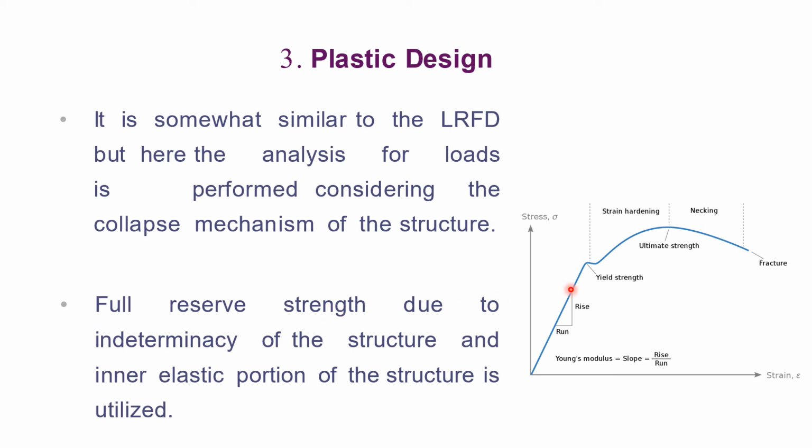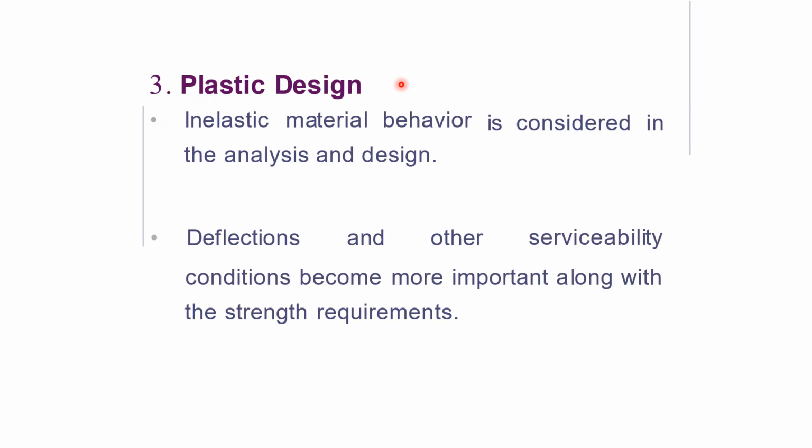Full reserve strength. You can say this is the reserve strength. We use LRFD only within the elastic range, not going into the plastic range. But in plastic design we also go into this plastic range, the permanent deformation. Full reserve strength due to indeterminacy of the structure, the inelastic portion of the structure is utilized. Means in plastic design the full strength, the elastic region plus the plastic region, is used. That is the methodology, or the philosophy, of plastic design.